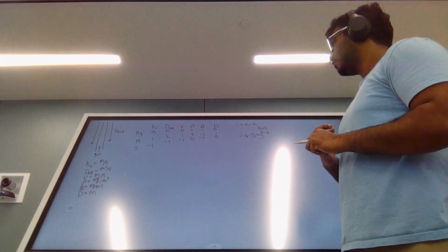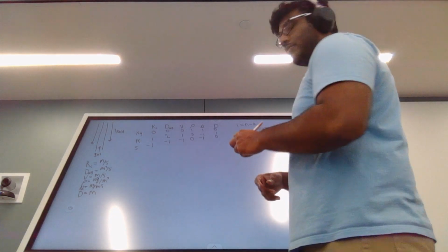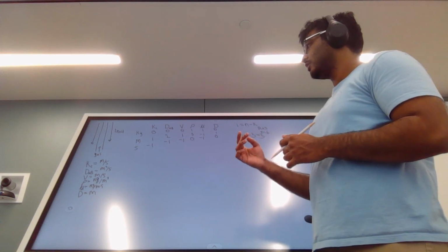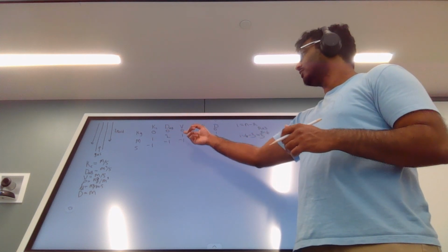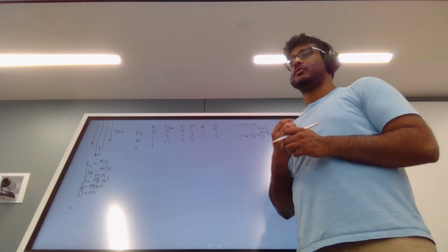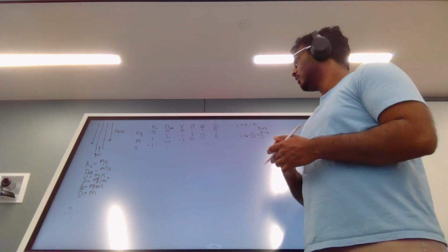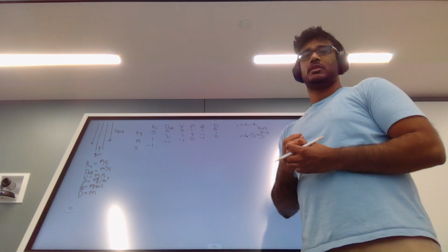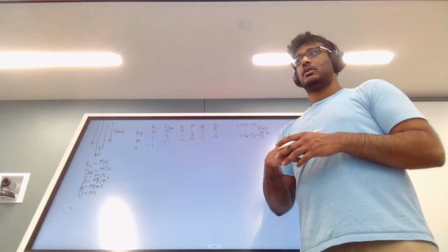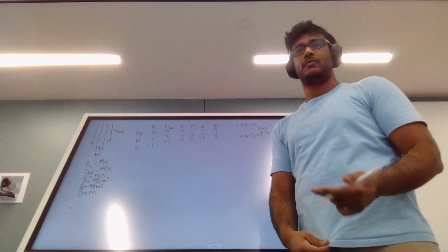So now since we know that there need to be 3 dimensionless groups, we're going to choose the variables we want to isolate. I'm going to isolate our mass transfer coefficient, our velocity, and our viscosity. I choose the mass transfer coefficient because it can only be found during experimentation. I want to isolate the velocity because it's the same units as the mass transfer coefficient, so it's going to be easier to solve for later down the road in the problem. And then I choose viscosity because we need to choose another variable to isolate.